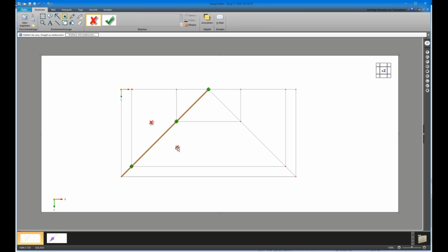And how do we get it? We get it by taking 50% of the span length. Now we can measure our tributary length by measuring this distance, depending on the projection plane and so on. But when we are in the projected area, we can use this value directly. And the tributary area in this case is exactly here, this purple highlighted area.